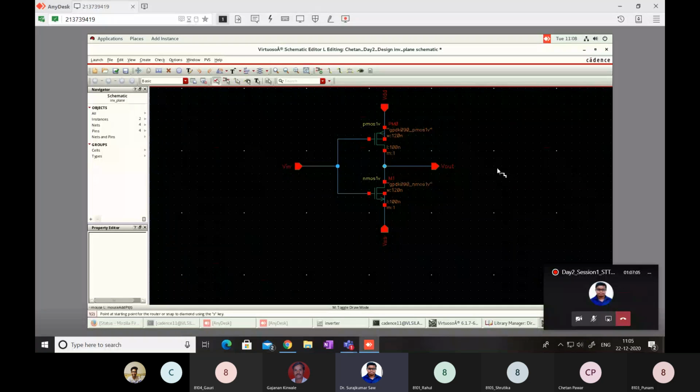The pulse width is always half of the period. If you have given the period as 100, then the pulse width will be 50. But with a rise time of 10 nanoseconds and a fall time of 10 nanoseconds, the average of these two will be 10 only. So we will subtract 50 minus 10. That will be 40 nanoseconds, right? You just need to take half of the period and subtract either the rise or the fall time.